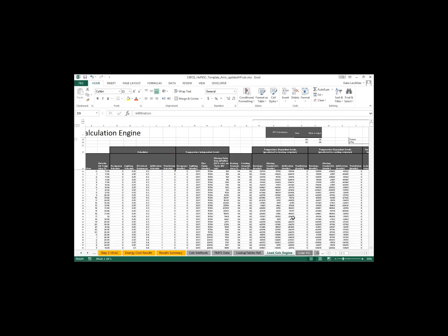So my other question is complexity. The reason we use EnergyPlus is because it's so involved and there are so many inputs, and you can really get into the nitty-gritty of what a building does. eQuest is a little more simplified. There are the same inputs, but not as many, I would say. You can't do the custom algorithms, that sort of thing. How much time does this save?